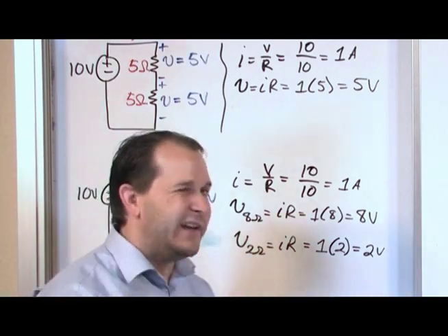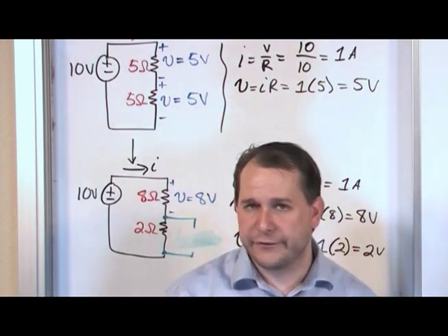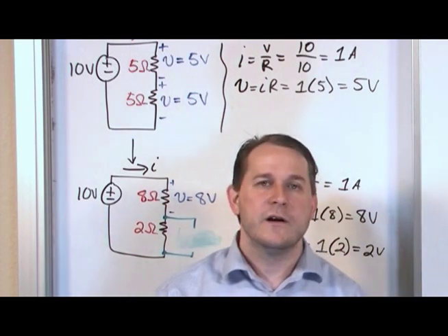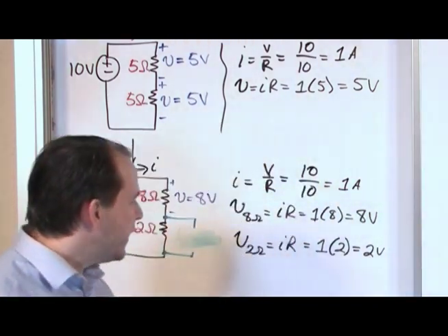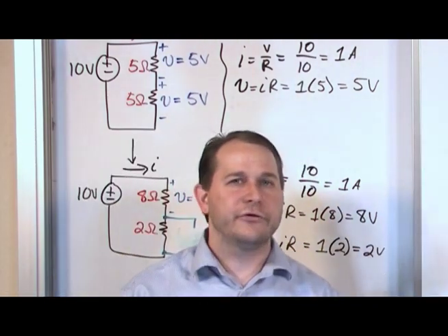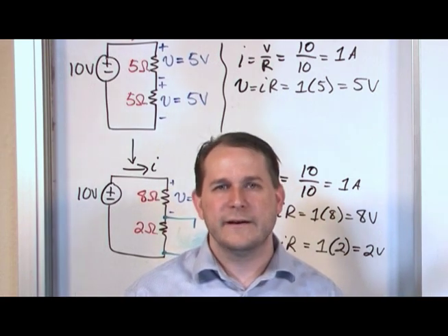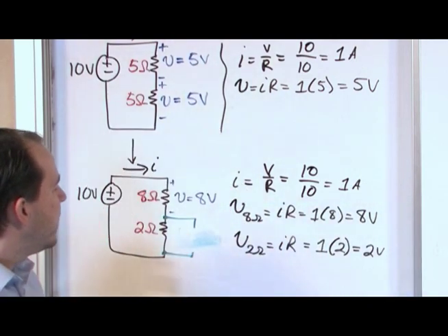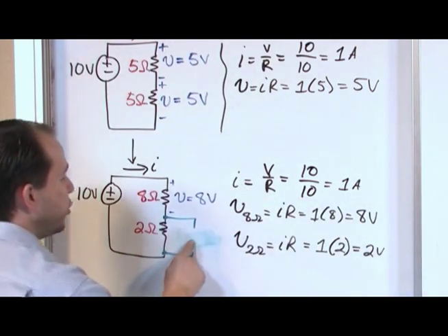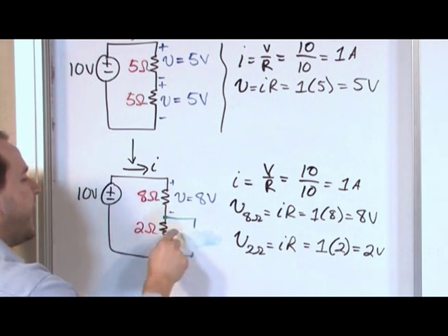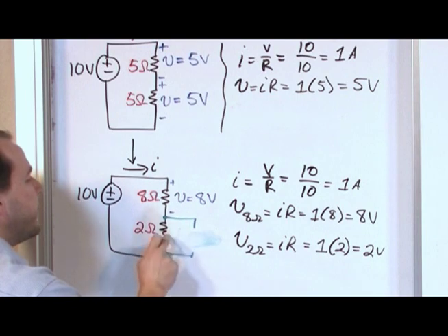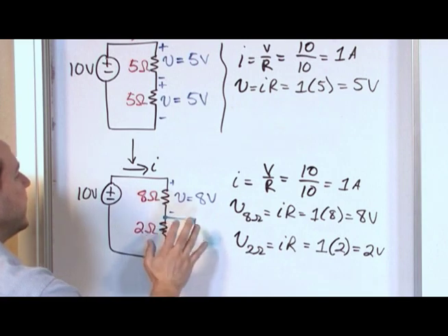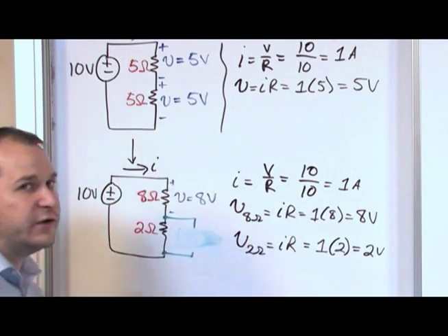Now when you think about it, as soon as I connect the load, which is some resistor, right? Like if it's a light bulb, it's a resistor. That's what a light bulb is. So let's just pretend it's a light bulb for the sake of discussion. So I hook a light bulb up to this. At the moment I hook a load up to it, then I've altered the circuit. It's no longer pure the way I originally designed it. If I hook a light bulb up to it, I'm introducing another resistance here. And if I put another resistance here, the resistance of the load, then this resistance is in parallel with my 2 ohms. So if I put the wrong kind of resistance here, I can change the value of this whole area of the circuit, which will alter the voltage going into my load.